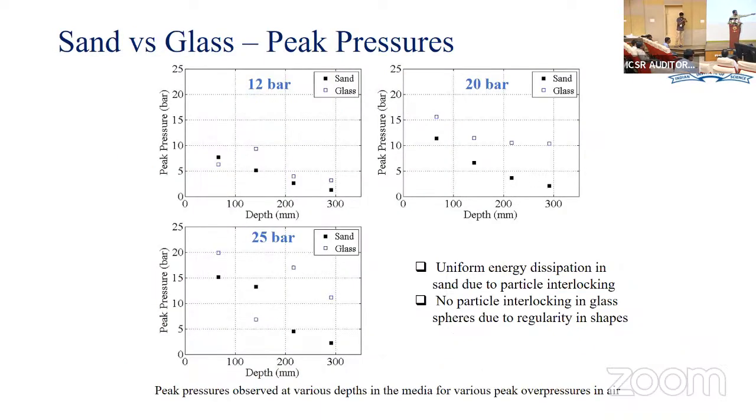So you pointed out the correct thing only. We are trying to come up with a length normalization also. Here we can normalize the pressure, meaning the peak pressure at a point by the peak pressure of that intensity of the blast wave or the reflected blast wave. But since we are not dealing directly with explosives, we cannot directly use those Z values, the characteristic length values. So we are trying to come up with something which can correlate these things, because more or less this comes out to be at the same location, same point, which should not be good.